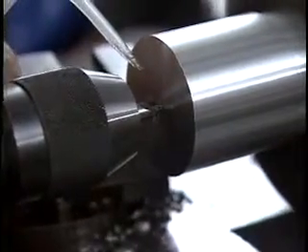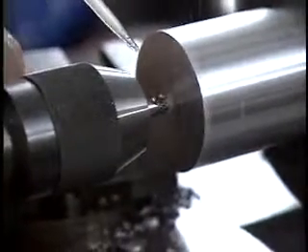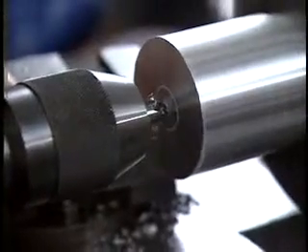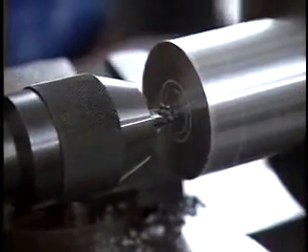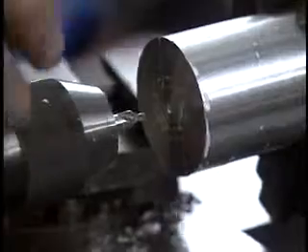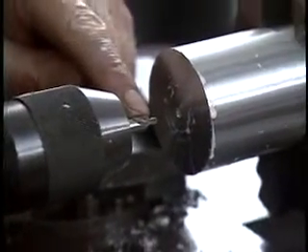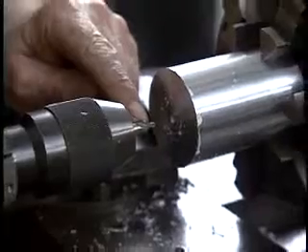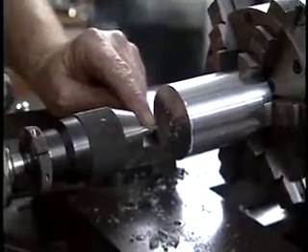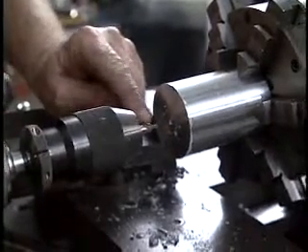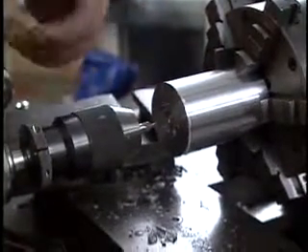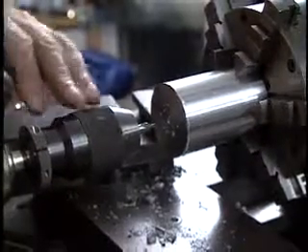When using a center drill, it's almost always a good idea to use a little bit of cutting fluid. This drill doesn't cut as well as a regular drill because it's a compromise between cutting like a regular drill and being very stiff. The result is that the chips that it produces don't clear out of the drill as well, because these flutes aren't as deep, nor do they have as much of a twist as a regular drill.